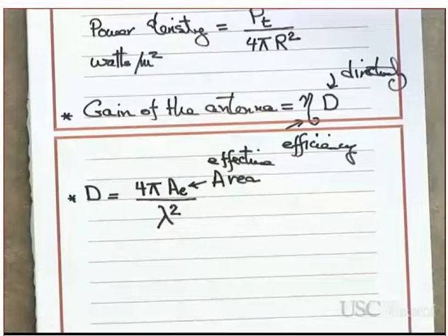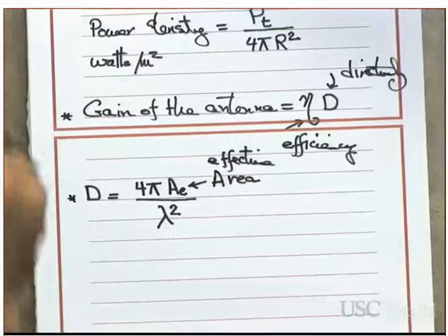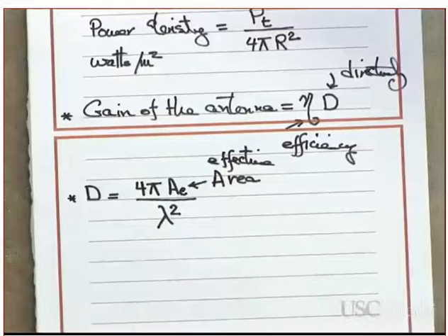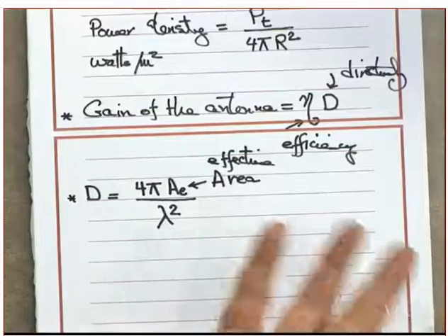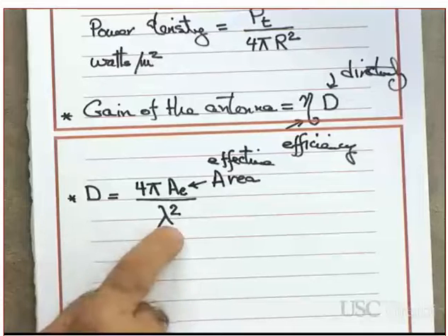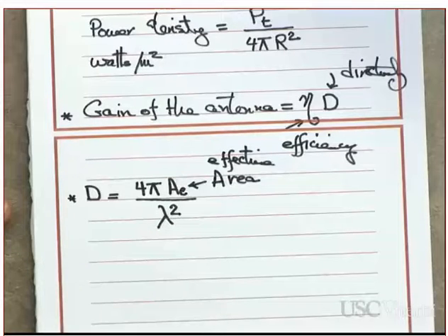We will see also that the higher the frequency, the degradation is higher. Why? Not because of the propagation over the free space. Propagation of free space should not depend on the frequency. Do you understand that or not? But because of this term, the directivity of your antenna. The geometry of the antenna. Did you understand what I just said or not?